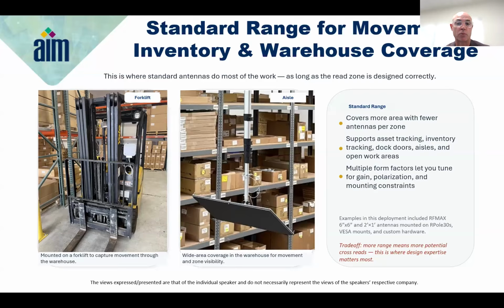I'm just going to address the circular polarity question, which is, we sell at Arcadian a lot of different antennas for a lot of different applications, and by the way, they're all linear, except in the RFID space. In the RFID space, you can use linear antennas where the RF pattern moves only in one plane, one direction, or circular polarity, which is essentially a spinning of the RF signal. Now, why do we typically default to using circularly polarized antennas in RFID? The reason is because we typically cannot predetermine tag orientation.